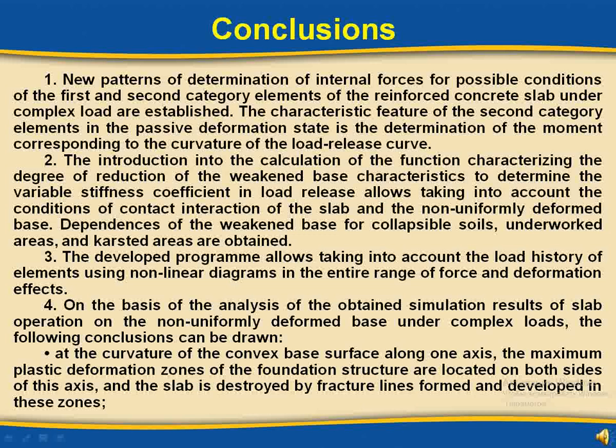1. New patterns of determination of internal forces for possible conditions of the first and second category elements of the reinforced concrete slab under complex load are established. The characteristic feature of the second category elements in the passive deformation state is the determination of the moment corresponding to the curvature of the load release curve.